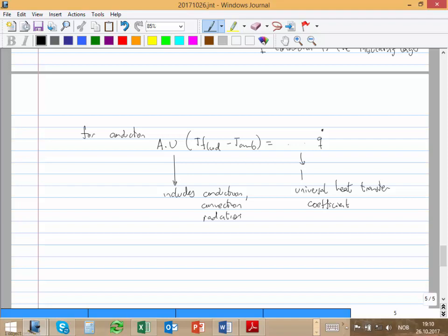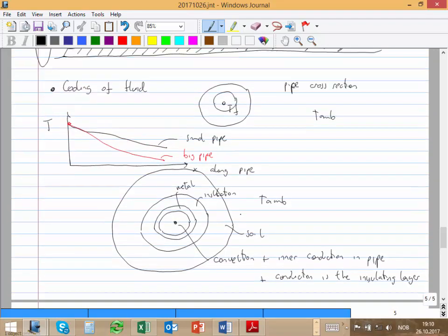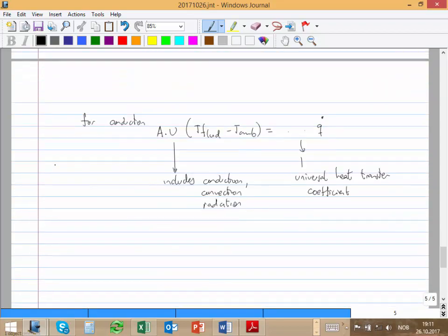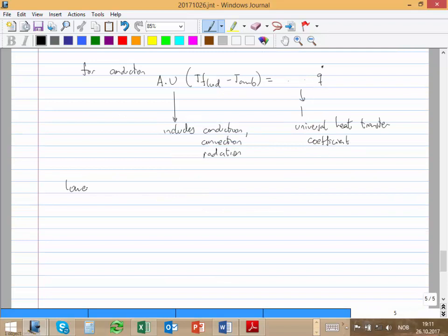So we cool, and you say, okay, that's interesting. The temperature goes down, but why is it a problem that the temperature goes down? Condensation, you get more liquid, it becomes a problem. I'm writing everything down, but maybe you're taking your notes, so just let me know if I'm writing too much. Lower temperature means more condensation of liquids, which is again the problem of slugging.